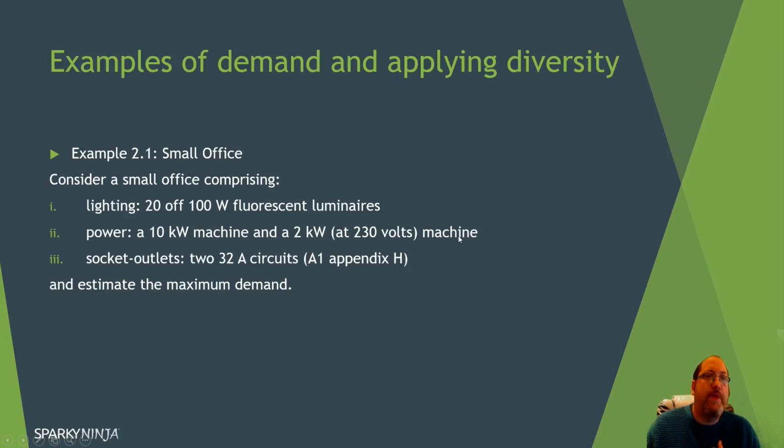So we've got 20 times 100 watt fluorescent luminaires. Now with fluorescent luminaires, we also have to take into account the 1.8 factor, which you'll see in the books, which explains the control gear issue, unless the manufacturer's given us another value. We'll see that in a minute.